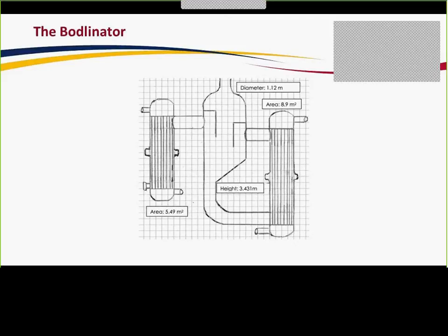The way that this unit operation works is liquid cool methanol feed is fed into the bottom of the left-hand side of the first shell and tube heat exchanger, and as the liquid levels rise and some of it is vaporized due to the heat transfer between the reactor effluent and this cooled process, the vapor liquid biphasic system comes out of the top, comes into contact with that baffle, and that top weir is meshed, which allows vapor to disengage from the liquid and flow out the top, whereas the liquid itself is drained out into